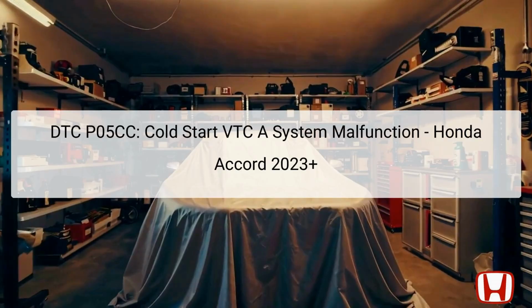Welcome to the debugging process for DTC P05CC, indicating a cold start VTC-A system malfunction in the Honda Accord 2023 and newer models. This error occurs when the engine control module, PCM, detects an out-of-range phase difference between the phase control command and the actual position of the intake camshaft.